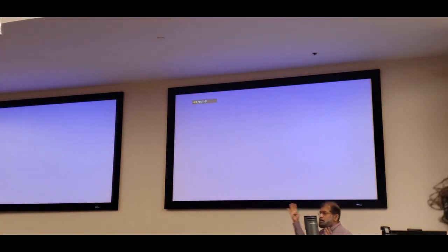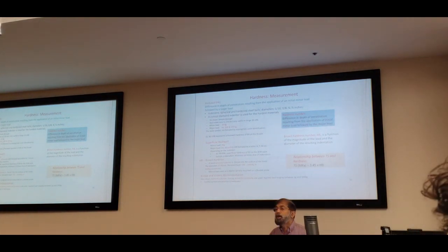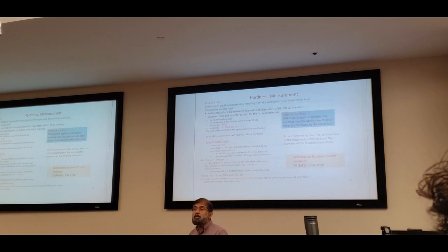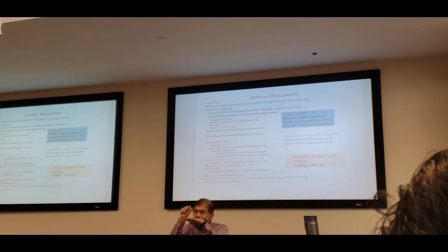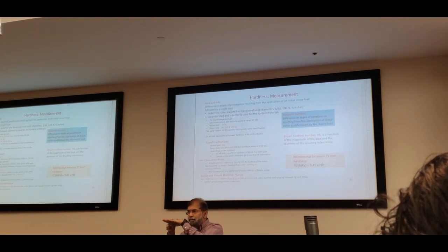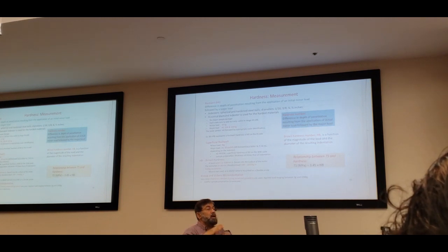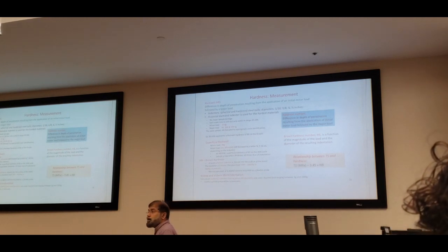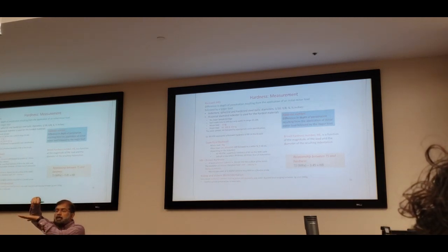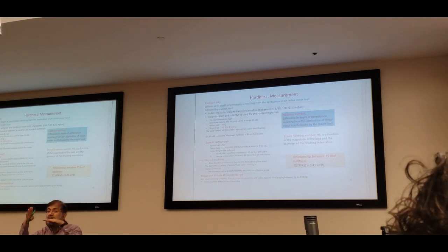Remember this. For Rockwell hardness, you use a minor load of 10 kilograms. We first use the minor load, and an indent is made, and then you apply a major load, like 60, 100, or 150 kilograms. Did you get it? Initially, a small load of 10 kilograms is applied, then a major load is applied.